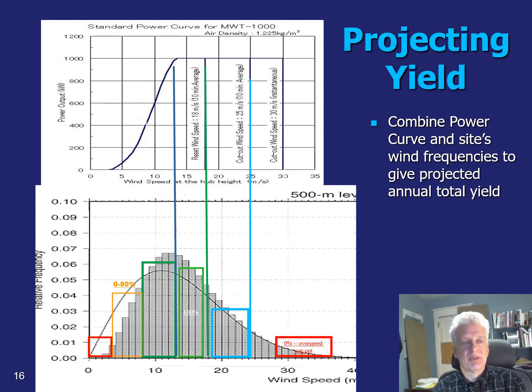And then to the right of that, the lighter green box, the wind is strong enough for the turbine to run at 100% all the time. Next, you get to the area where you might have to look at the cutoff. So if the wind moves up into the pale blue box, up to less than 25 meters per second, the system continues producing at its full power, and so all of these bins here might be able to have the turbine produce at 1 megawatt.